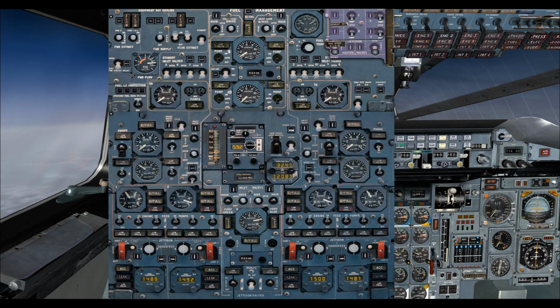And because tanks 1 and 4 are located closer to the front of the aircraft, the center of gravity, the CG, will move forward, probably around 0.5, but not enough to go past the forward bug and cause a problem for our aircraft, which is still in cruise climb.